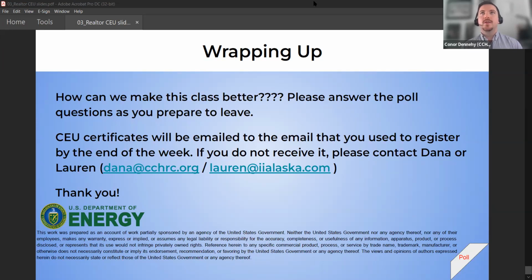And the only reason somebody's going to remove the refrigerant from the system, which I should mention, you have to have an EPA certification to deal with refrigerants, so it's not normally a homeowner DIY approach, is if the system's not working correctly and they have to look for a leak or something in there. You take all the refrigerant out, perform some diagnostics, and then put it back in if you're fixing a leak.